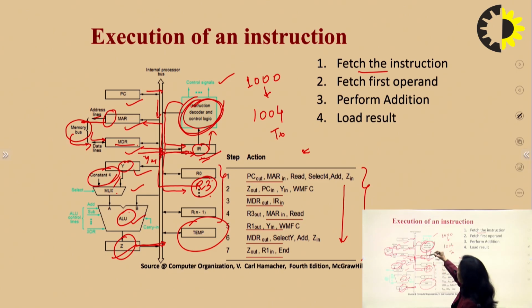Now, this instruction register will send the value of the address that was pointed to by the register R3, and via this control logic, it will again move towards the B register. This B register will be directly giving that number to the ALU.